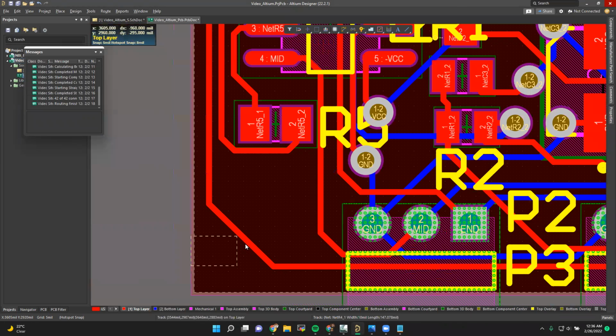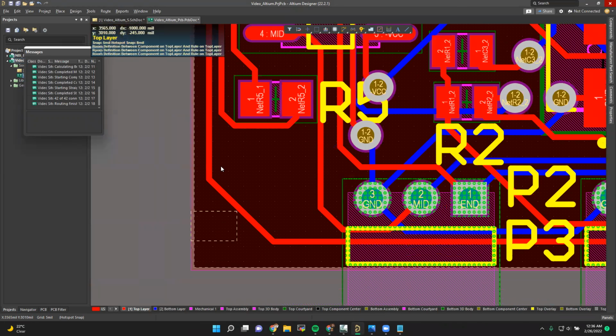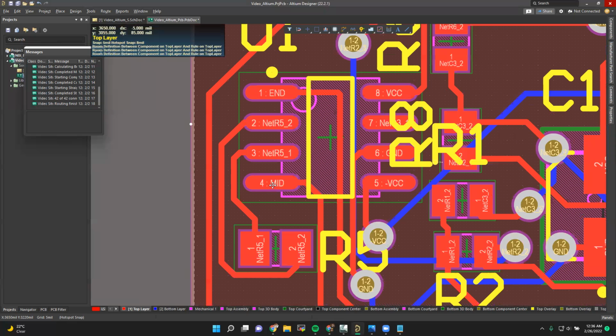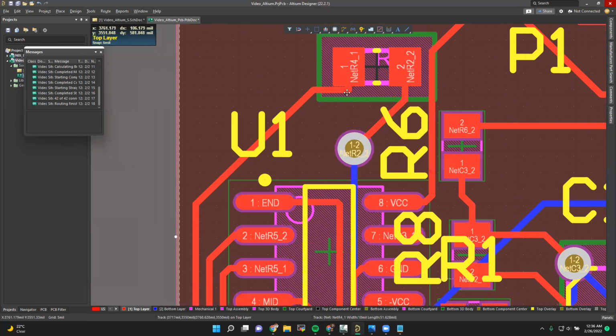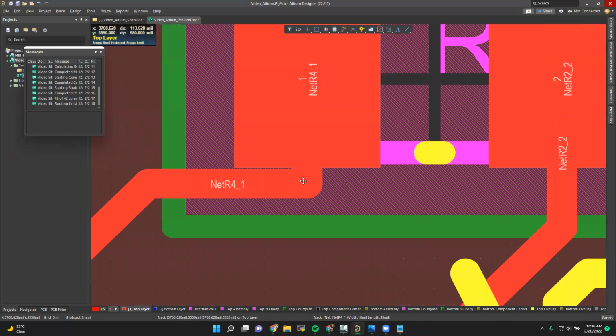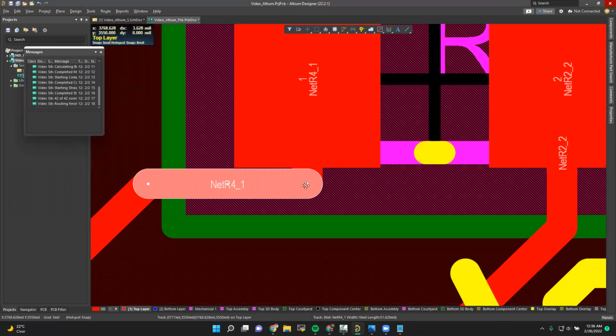This is something important. So what's easier? Let's say you're driving a car. What's easier, to drive on a straight line or to drive on a road that has a lot of turns? Obviously, it's easier to drive on a straight line. So it's the same for electricity. It's easier for electricity to travel in straight lines. You should always try to avoid this. You should try to not do this. 90-degree angles on traces are not good. You should always try to be below 45 degrees.